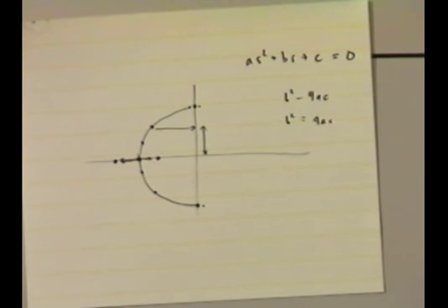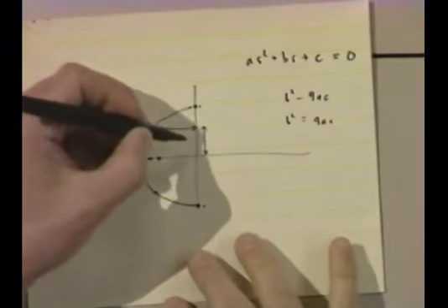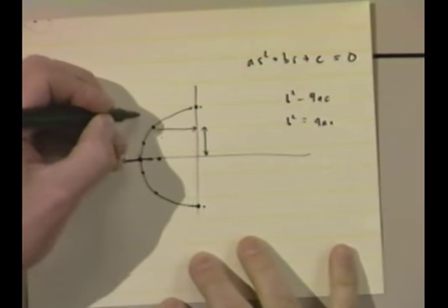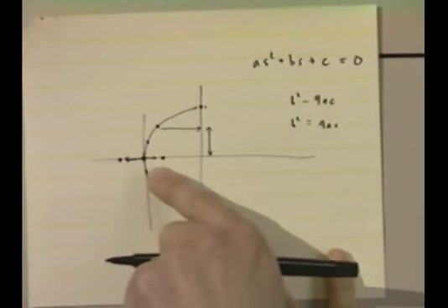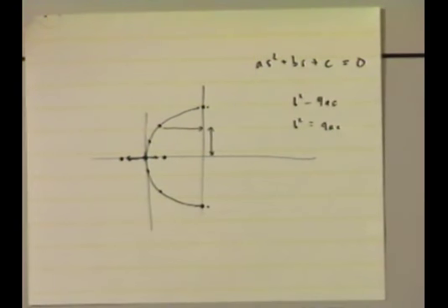Then you say, well, let me help you with some intuition. This new shock absorber, for a given velocity, is going to extract more energy. And then they go, oh, thanks for the hint. When I put the new stiffer shock absorber in, it's going to decay faster. And you go, good intuition. But you're totally wrong. This picture shows why the critical damping gives you the best decay rate. It's the farthest you can make both roots to the left. Everybody got that?